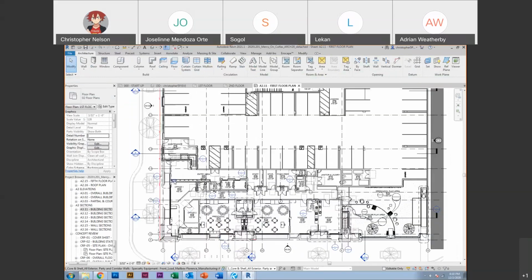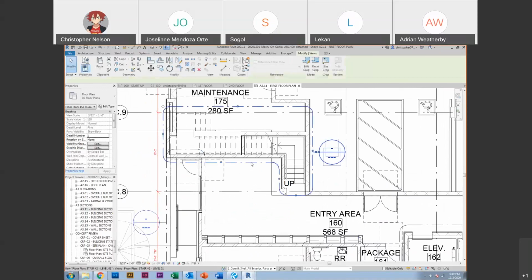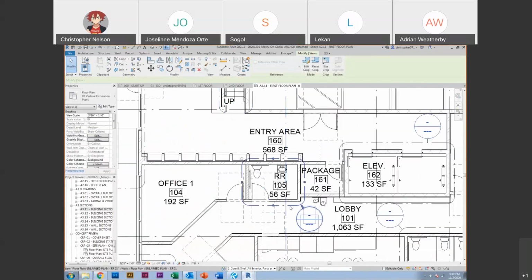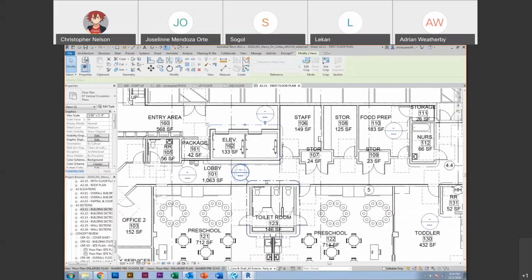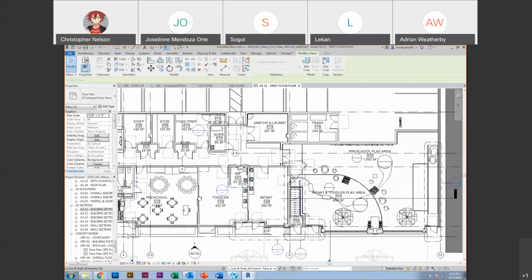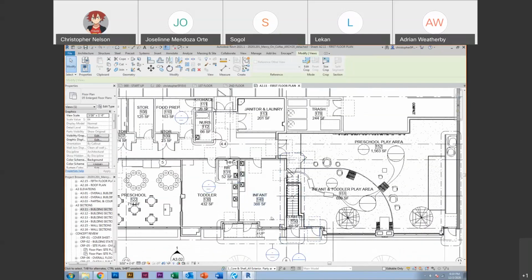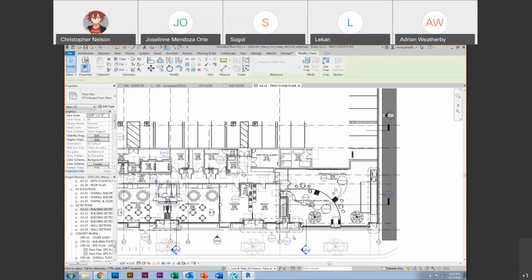So, all I did when I started this, I sheeted all the floor plans. I started cutting building sections where I thought I needed them, and then I also started making callouts here. You'll see I made a callout for this, and the bubble's empty. I haven't sheeted it yet in this model. Same thing goes for the bathrooms, elevators, more bathrooms, parts of the building, but you just cut all the information and you name it so it's ready to go, right?